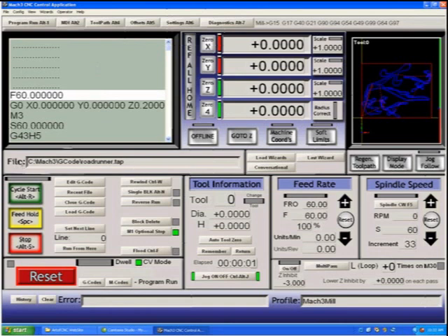Here we'll display the file name that you currently have loaded, and here's a reference button to send all our axes to 0, to our home switch. If we press reference, you'll notice that the y-axis is now moving up, and now it hit its switch, and now the x-axis is moving to its switch, hits it, and then backs off the switch.